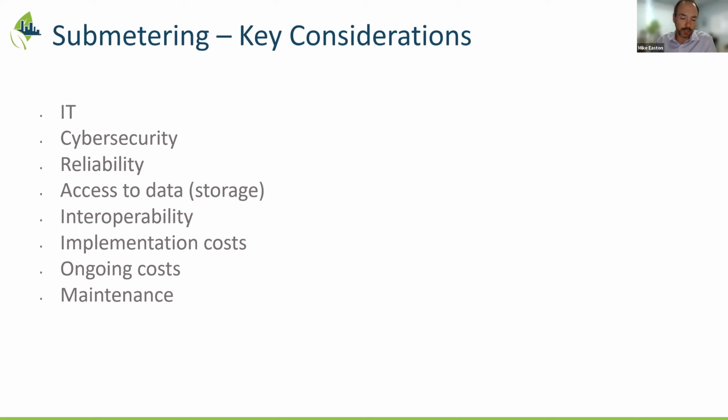Yeah, sure. You'd mentioned earlier that electrical meters were the mainstay of building level or sub-meter solutions, and that is very accurate. Because of that, electrical meters tend to have a very long field life. They typically don't need recalibration for around 10 years, but if you want to be on the ball, you could do it every 5 years. But with more mechanical metering being done, there's quite a variance in the re-verification and recalibration periods necessary.